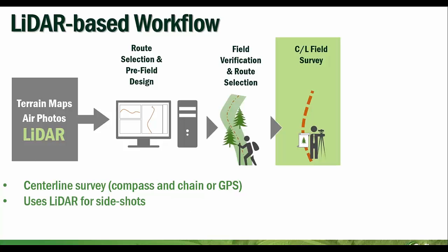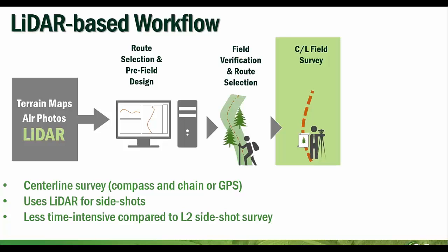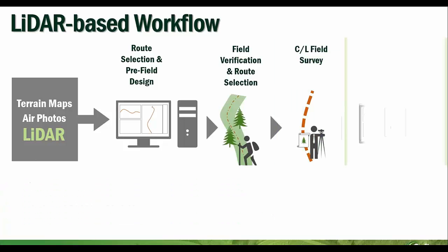One of the biggest benefits of LiDAR is you can actually use LiDAR for your side shots. Again, reducing the amount of time we're going to spend out in the field, which is significantly less time intensive compared to an L2 side shot survey.